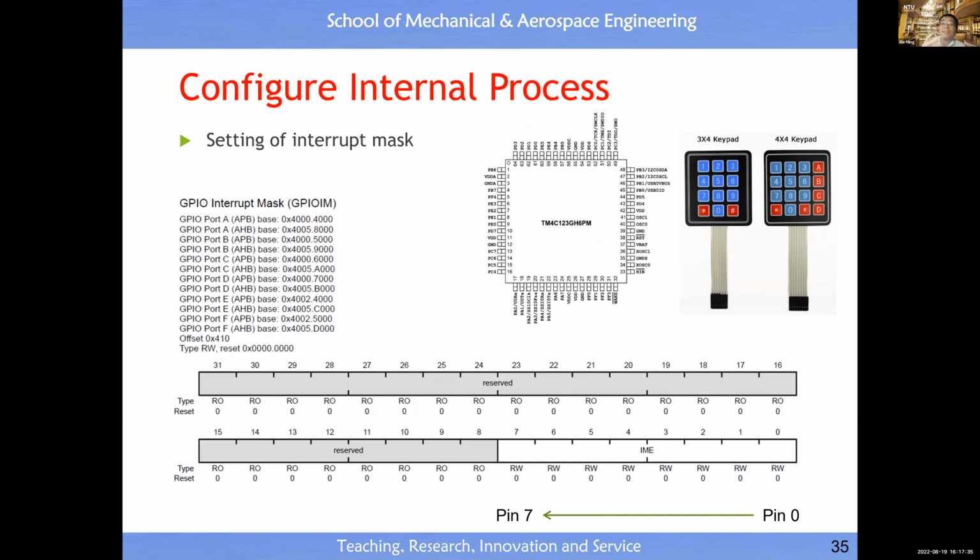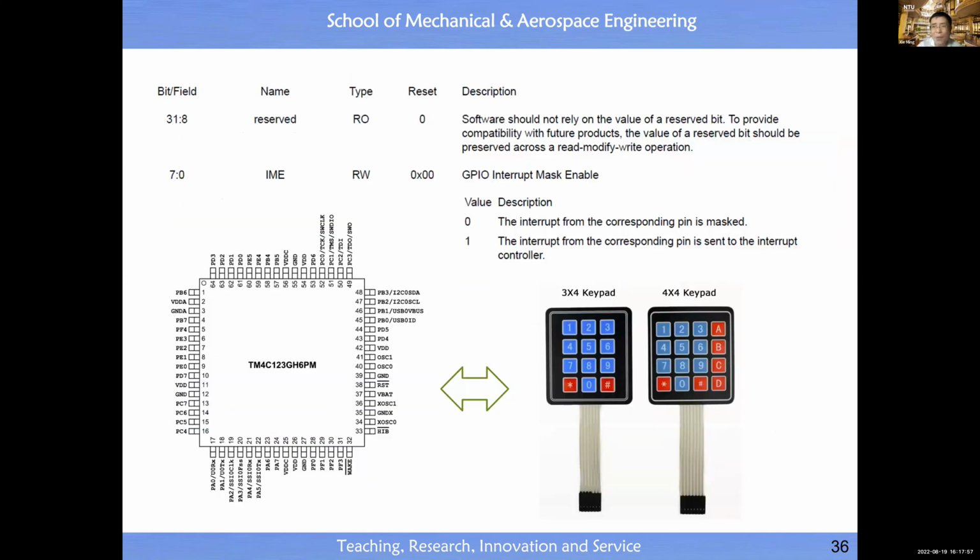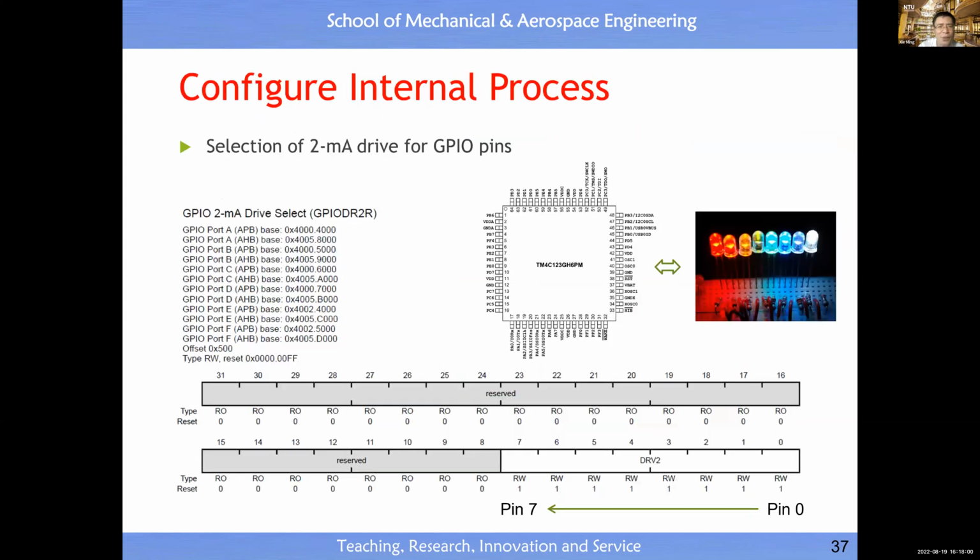Interrupt, you remember, is a signal, in this case a signal detected by the input pin. You tell the hardware what kinds of signal to respond to, and here you can mask them out dynamically. Depending on this period of time, I'm quite safe and I do not want to be interrupted by external signals. So you can do it. You see, it's very, very flexible.